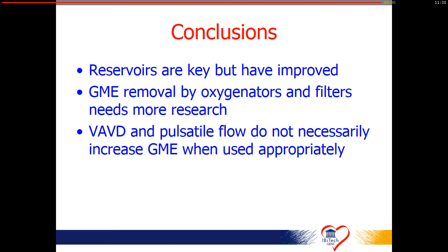But the question then is, how should that filter look like? Because I can tell you, based also on experiments we did ourselves, if there is air coming in such a screen filter, and it's partially captured in this filter, at that moment you start generating huge amounts of micro air. It's basically because this filter screen becomes dry, and there it will pass.